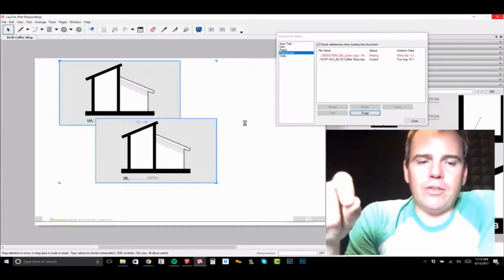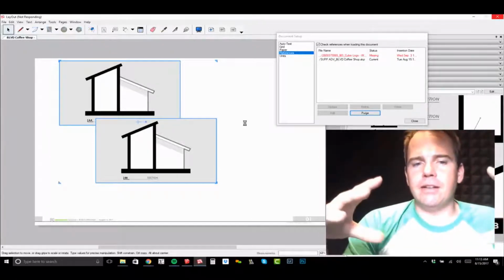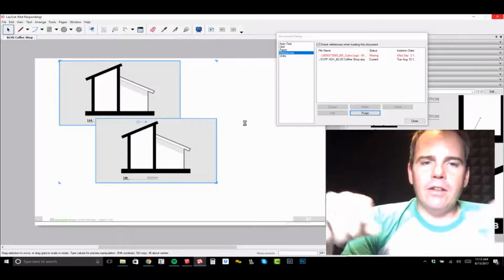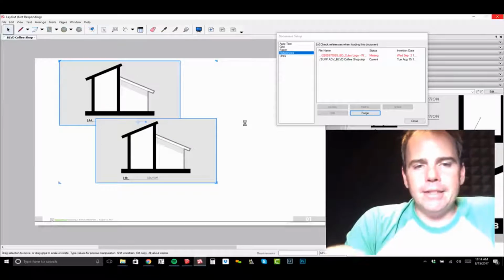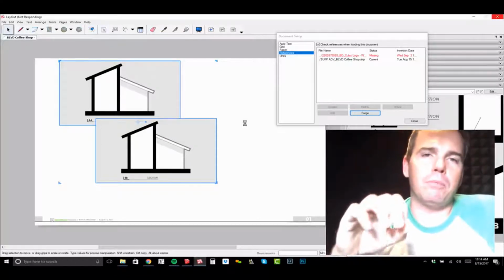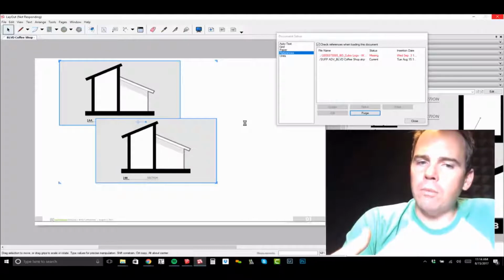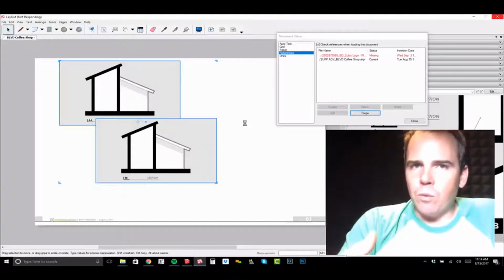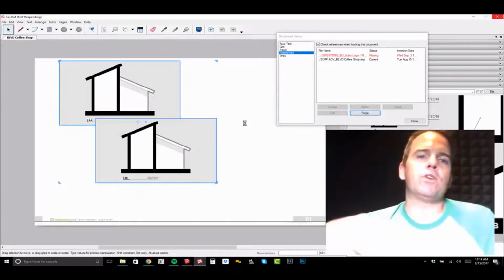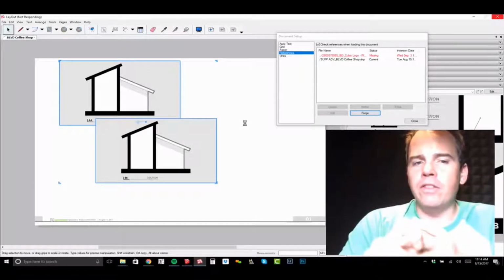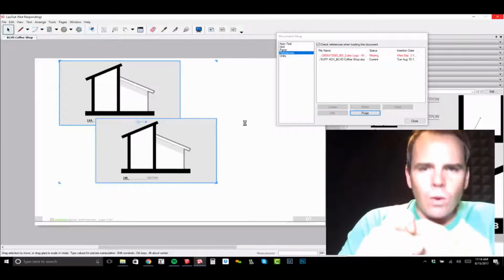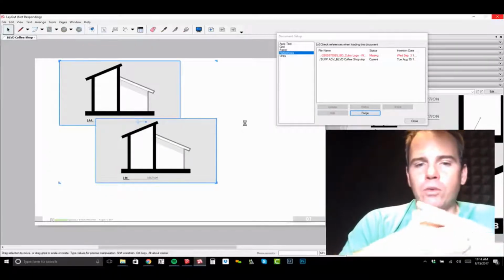The reason that happens, so first, this is an 11 by 17 piece of paper, and the style that I chose for these sections, being the presentation style, is pretty heavy. It's got a watermark, and it's got vector line work. It's rendering as a hybrid. So these sections and the elevations both render as a hybrid, which means it has to render all the vector line work once, and then it has to render all of the raster graphics and line work as well.